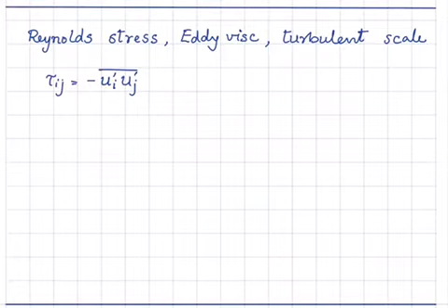So if you want to compute a turbulent flow and get the mean velocity profile, in a general 3D flow, you will have to get values for all these Reynolds stresses, which depend on fluctuations, so we cannot directly compute them. These are unknowns. These are like non-closed terms in the momentum equation.